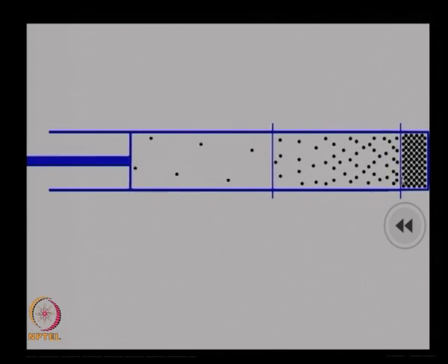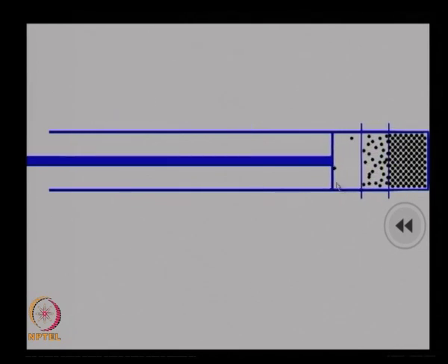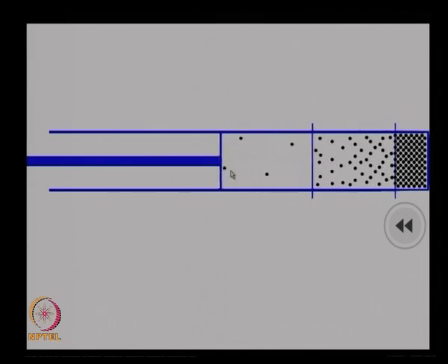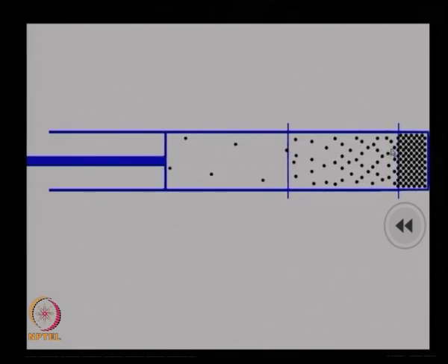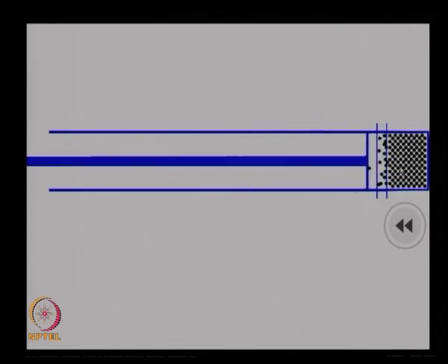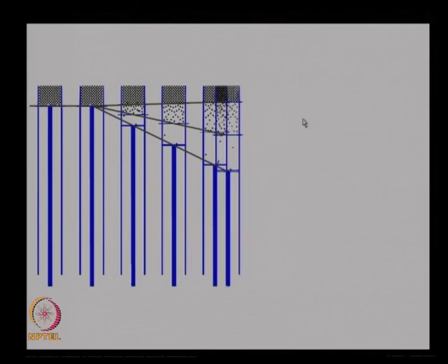This is the first expansion wave and this is the last expansion wave. Okay. And we already did the pressure plot of what this cross section will look like, pressure variation, last class. This is a 1D problem, but we will do the 2D expansion fan; we will look at that next.